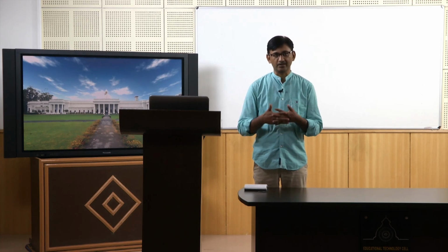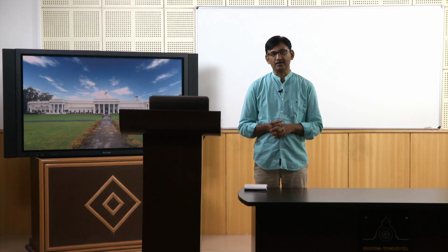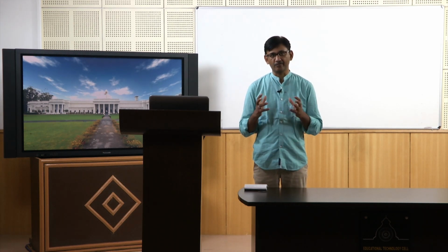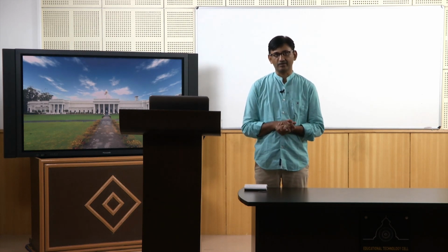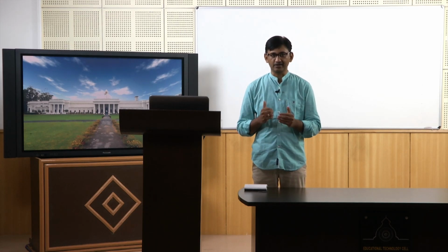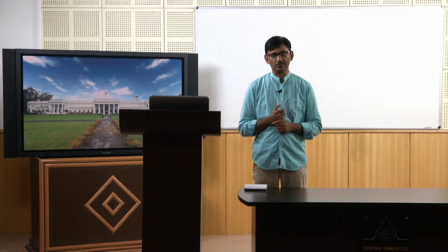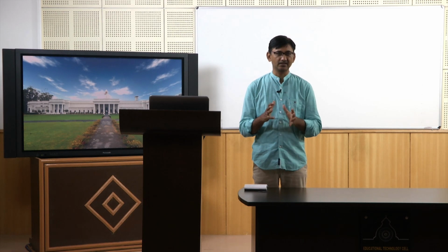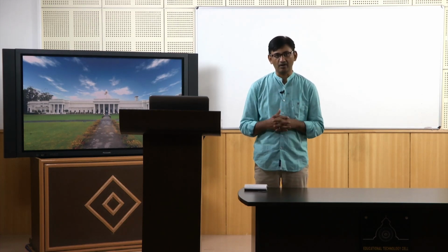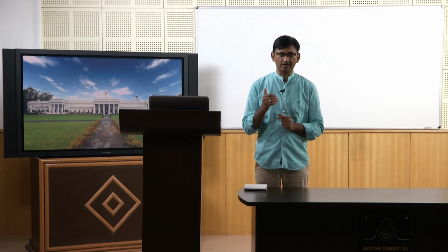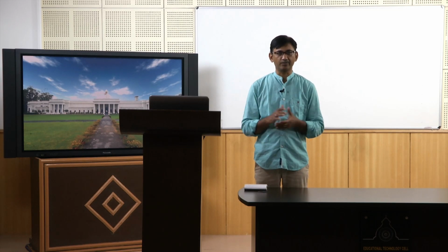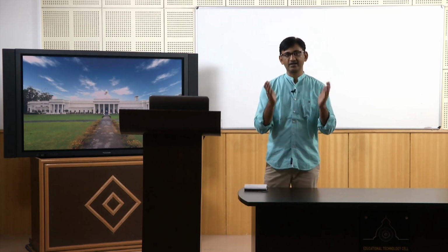So steel is a very well known material which is used in a lot of applications, structural applications mainly, and to have higher strength and hardness on the surface, we do a process called carburization. As the name suggests, it involves the diffusion of carbon in steel. You may not be knowing this right now, but steel is an alloy between iron and carbon. Iron and carbon make an alloy which is called steel. And carburization means that we want to introduce or increase the carbon percentage only on the surface of any component, to have more strength and more hardness on the surface. So the process with which we do this is called carburization.